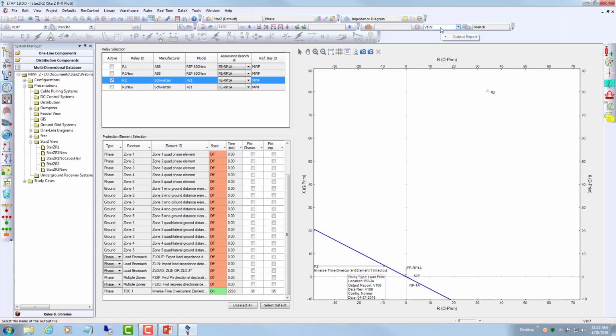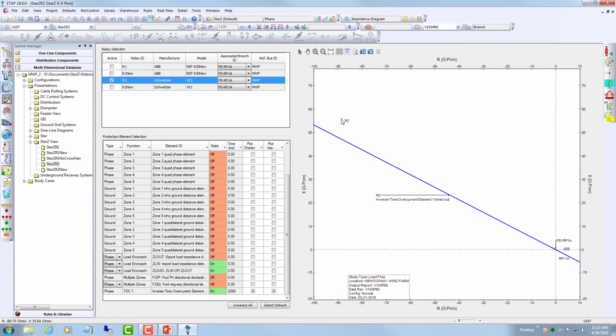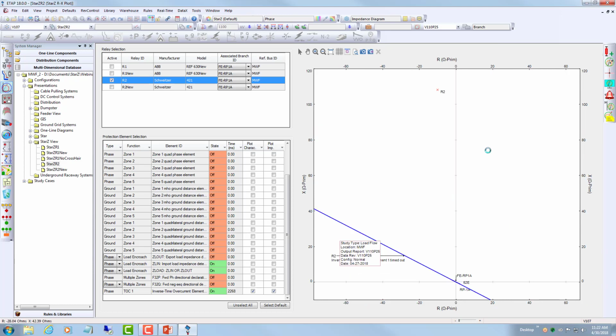Now if you look at the other side, the left-hand side of the graph, we look at 103 P25. Again, this has a lower current, basically below the pickup, so it's not going to trip. At 103 voltage and P60, we had a trip also in the ABB relay, but with very little margin. Here we have more margin, so there will be more chance of false tripping. Then at 110 again we're going to have a trip too. So both relays, as you see, have the potential of false tripping.